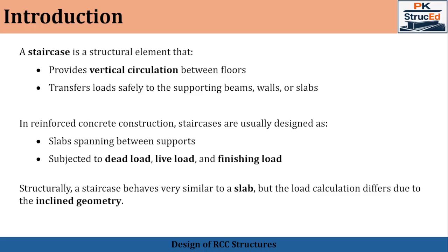A staircase is a structural element that provides vertical circulation between the floors, and it transfers the load safely to the supporting beams, slabs or walls. In reinforced concrete construction, staircases are usually designed as slabs spanning between the supports and subjected to dead load, live load and finishing load.